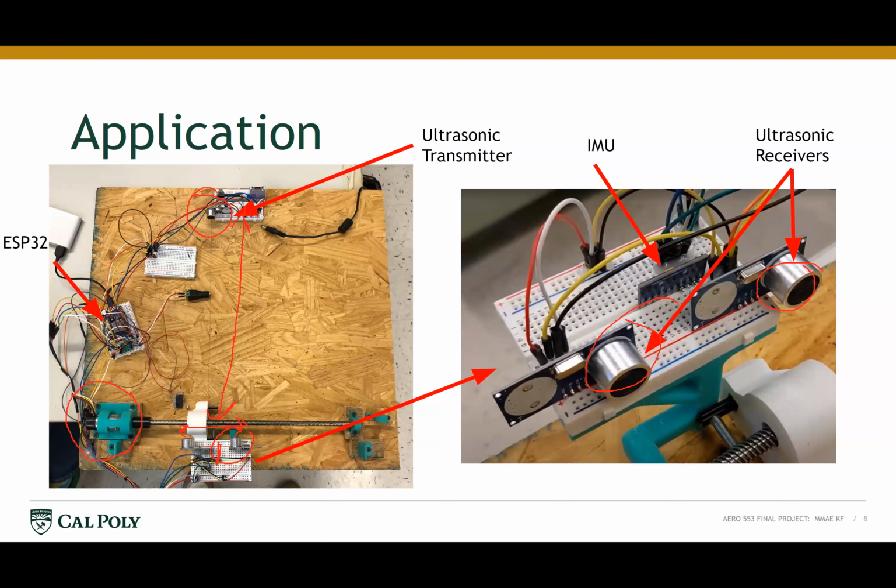The third method is using this IMU here, which is at every given point giving you an acceleration reading in this X direction, which we're defining as the direction of the linear screw. If you integrate that acceleration twice, we can get position. So those are our three basic methods of getting position.